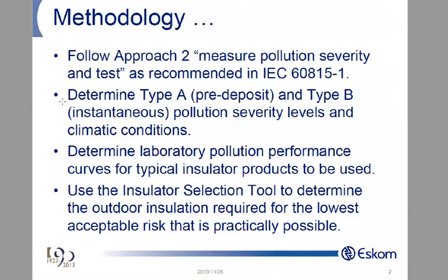Then in doing that, I need to determine the type A pre-deposit pollution and type B instantaneous pollution and the severity levels and climatic conditions for that area. I need to go and determine laboratory pollution performance curves. And then I need to come back and use the stats.